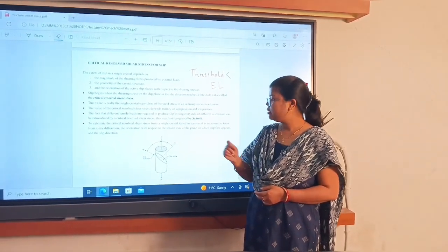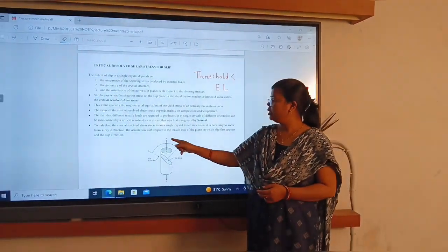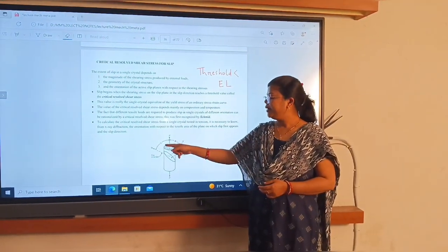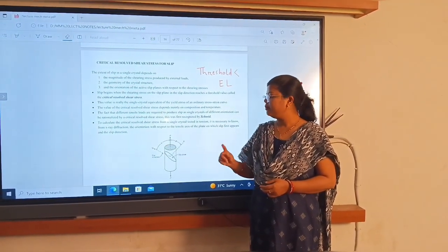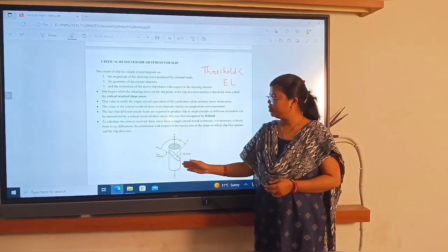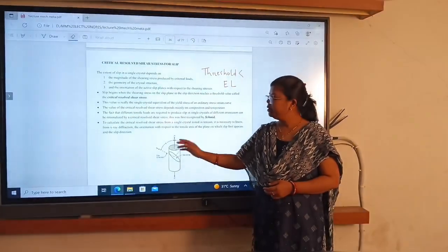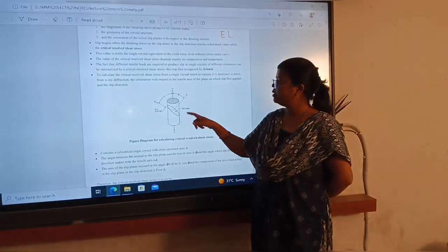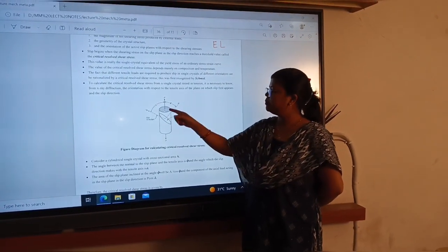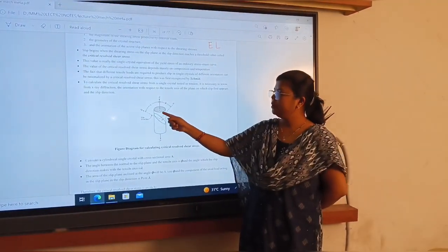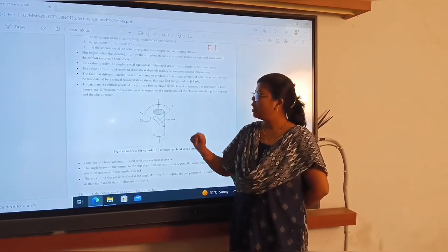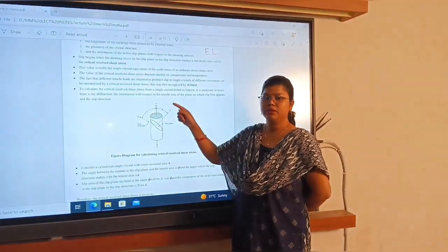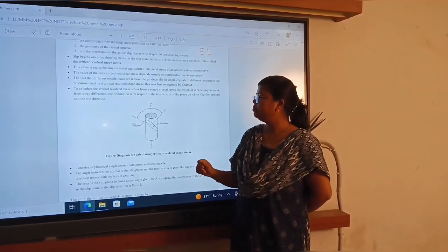The angle formed between the load and the normal will be called phi, and lambda will be the angle between the external load applied on the cylindrical body and the slip direction. As shown in the diagram, A is the area of cross section, N is the normal to the slip plane, and tau r is the slip direction, where P is the external load applied on the top and bottom of the body.